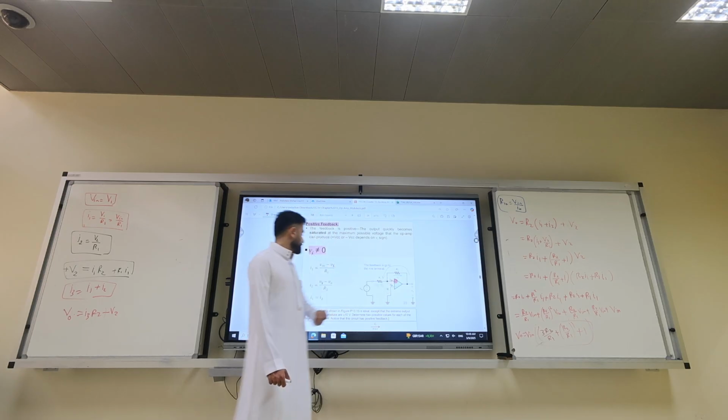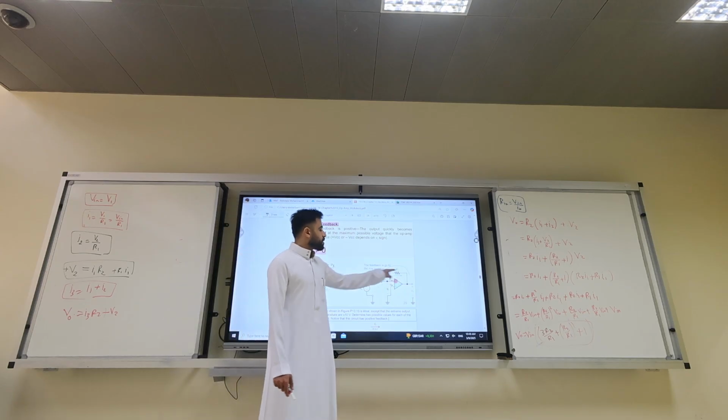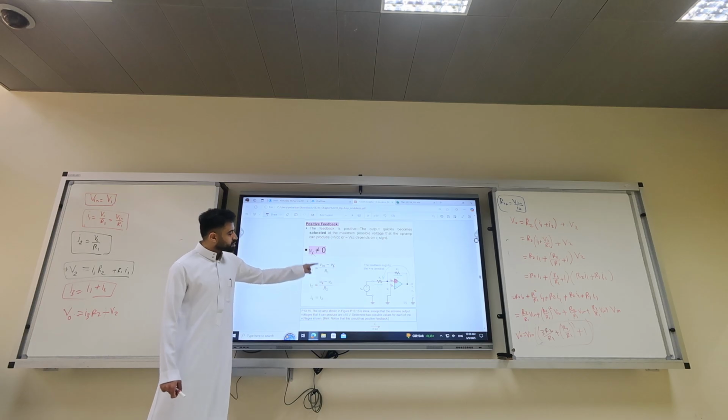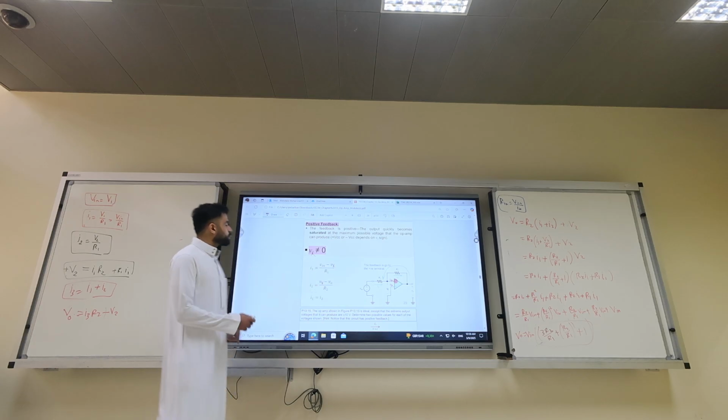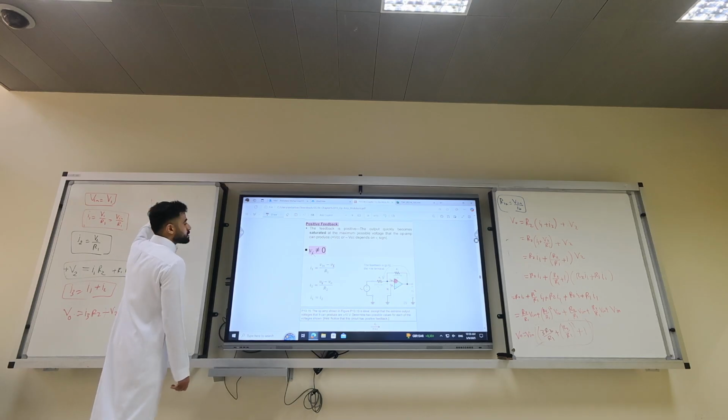They block the currents. So the feedback goes to the positive terminal. And if I want to find the relationship between V output and V input, I know that V input minus Vx over R1 equals Vx minus V output over R2.